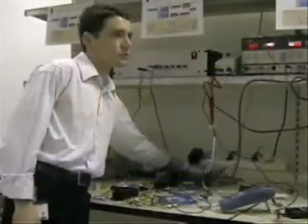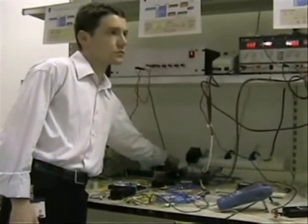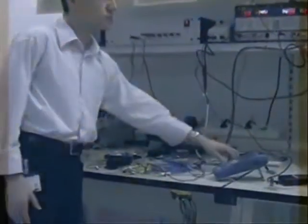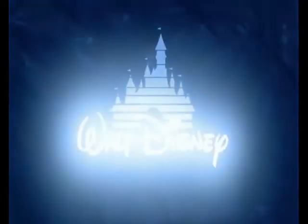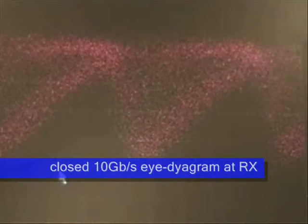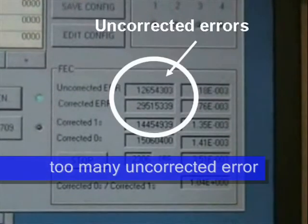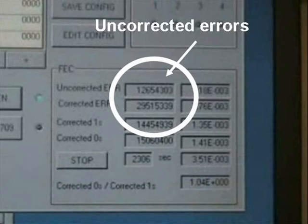The optimization of the demultiplexer in terms of polarization and synchronization is the most critical aspect of the experiment, mainly due to the absence of the clock recovery. A bad choice of the demultiplexer parameters induces a degradation of the received eye diagram up to a complete closing. In this case, the number of errors at the receiver increases too much to be corrected by the forward error correction, and the transmission is lost.